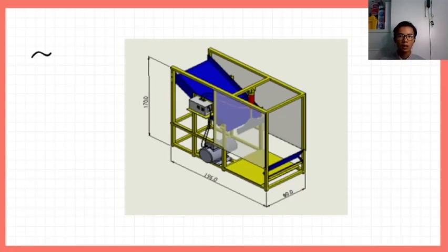This is suitable enough for our machine because we have made a calculation about the height of the slider. If we fabricate the slider lower than 140 centimeters, the slope of the slide will not be steep enough for the sugarcane to have the gravitational effects. So the sugarcane will not slide smoothly towards the stopper, and the cutting mechanism will not work.